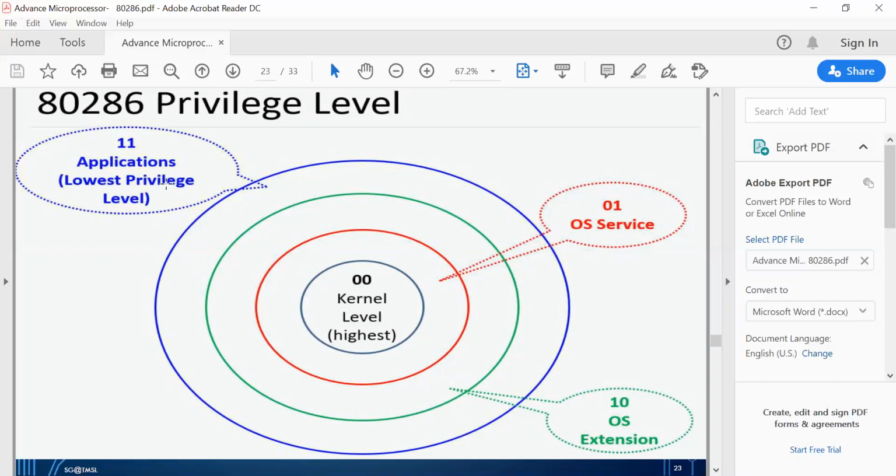The privilege mechanism offers or denies access, and privilege controls the use of instructions and descriptors. The capabilities of the privilege mechanism are exercised using different privileged instructions available in the 80286, and different privilege types such as task privilege, descriptor privilege and selector privilege.